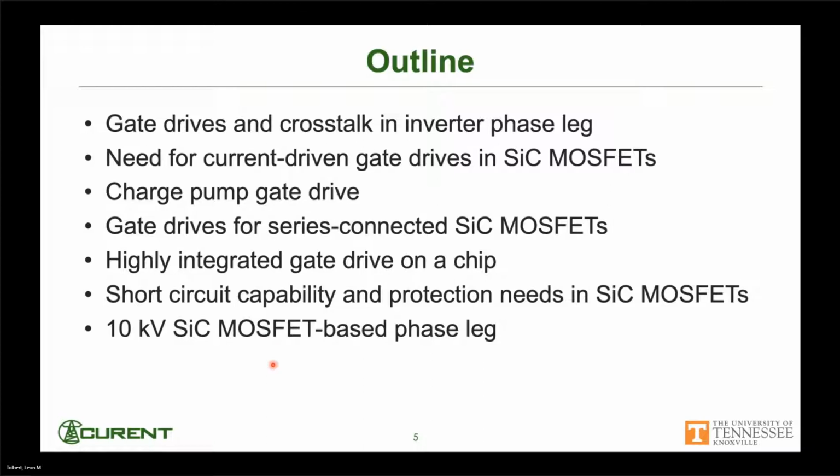So this is an outline of what I want to try to cover today. We're going to talk about gate drives and crosstalk. We're going to talk about some novel gate drives in addition to voltage source gate drives: current driven and charge pump. Look at some of the issues with series connected silicon carbide MOSFETs.